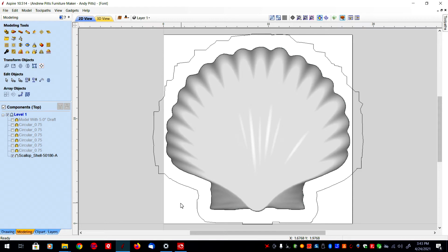I'm using a 3-inch thick block of material, and typically a long bit might be 3 inches long, but you have to stick an inch into the collet, and the cutting length on a long bit is usually not more than about 1.5 inches. So I had to really think about how I'm going to be able to cut into a 3-inch block and go pretty much all the way through the full thickness.